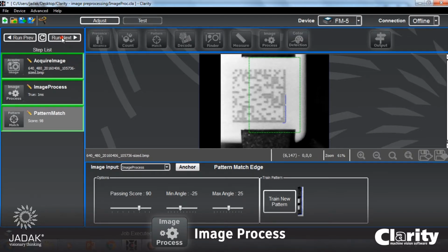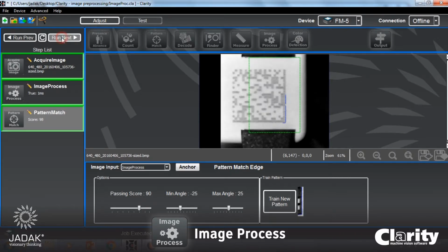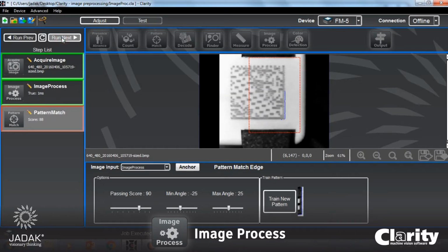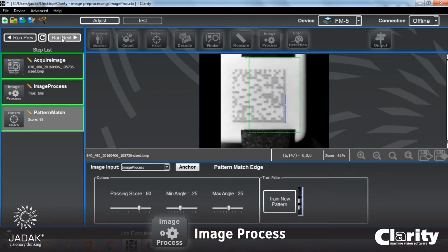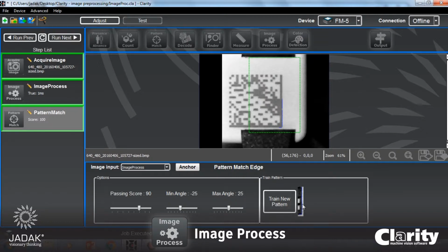It's somewhat successful on most of the images in locating a clean edge, but as you can see by the red box, some of them are scoring low as far as a match of pattern. Most of the times the mismatch occurs when there is some notably dotted edge pattern that it's trying to match the training pattern of a straight line with.